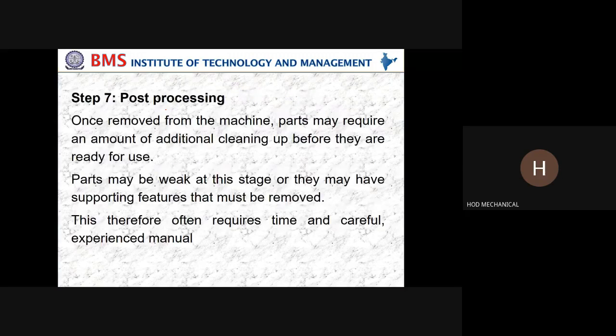Then post processing. Once removed from the machine, parts may require an amount of additional cleaning up before they are ready for use. Parts may be weak at this stage, or they may have supporting features that must be removed. This therefore often requires time and careful, experienced manual work. Now this is very important: some post processing is going to be required.